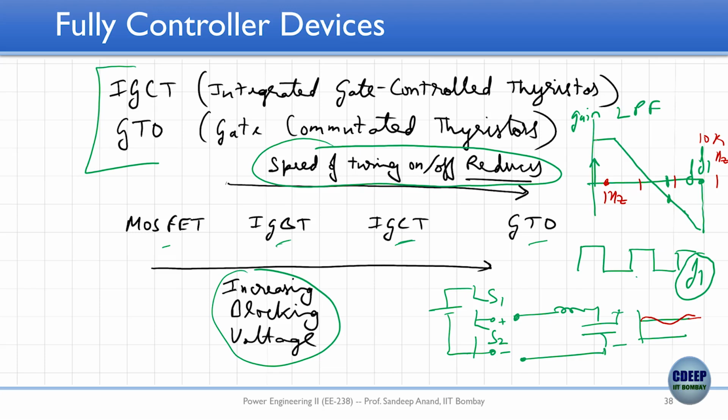So hypothetically I have to design a filter so that at 1 hertz also I get sufficiently large negative attenuation. And to do that, what is the cutoff frequency? Omega is 1 by root LC. If my cutoff frequency is very low, then either the inductor has to be large or the capacitor has to be really large, or both of them have to be really large.